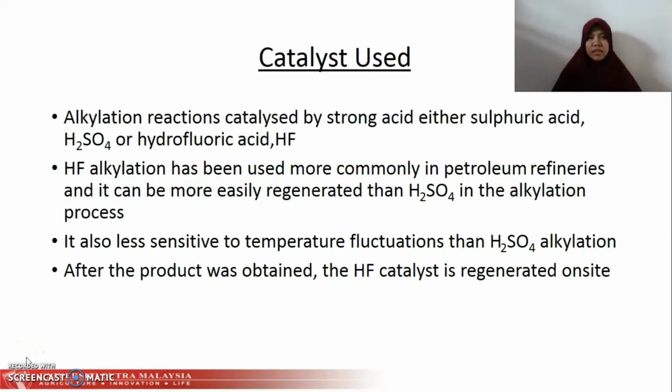Alkylation reaction is catalyzed by strong acid, either sulfuric acid or hydrofluoric acid. Hydrofluoric acid alkylation has been used more commonly in petroleum refineries, and it can be more easily regenerated than sulfuric acid in the alkylation process. It is also less sensitive to temperature fluctuation than sulfuric acid alkylation. After the product is obtained, the hydrofluoric catalyst is regenerated on site. Therefore, in our process, we use hydrofluoric acid as our catalyst.